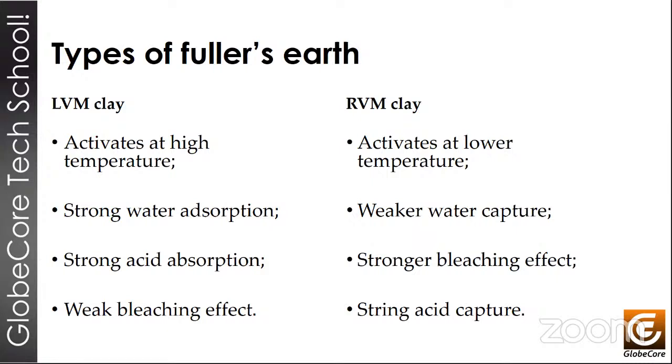And just a quick side note here. Using Fuller's Earth to remove water is not something I'd recommend, because there are more economical and simpler processes for that. We can use thermal vacuum processes, for example. And the thermal vacuum process does not involve any consumables, right? It's just a vacuum chamber, basically a filter. But Fuller's Earth, there comes a moment when it's saturated and it needs to be disposed of in some manner, okay? And Fuller's Earth, when it's saturated with these contaminants, it's a hazardous waste, so its disposal can be quite expensive. But good news, and I'll come back to that in just a few minutes, Fuller's Earth can be reactivated and reused up to 300 times, depending on certain specific process parameters.